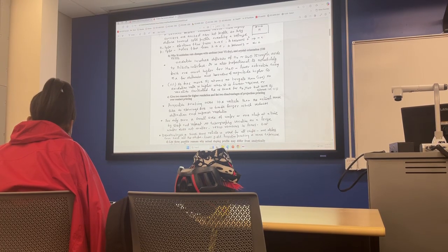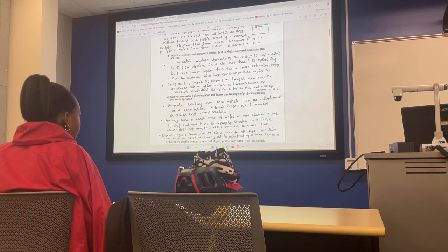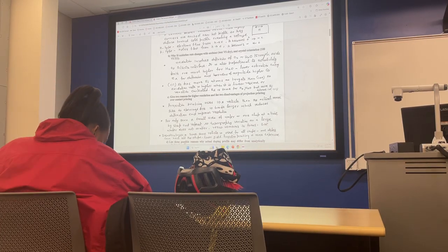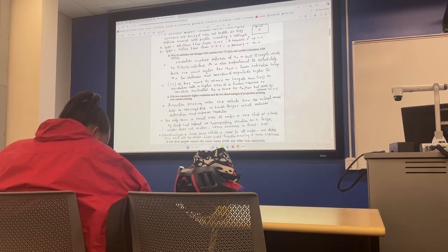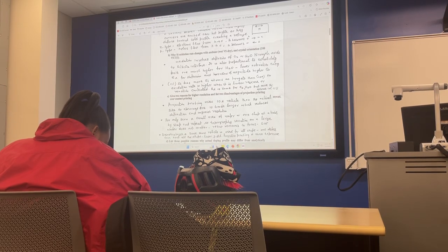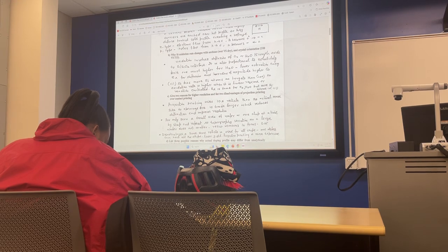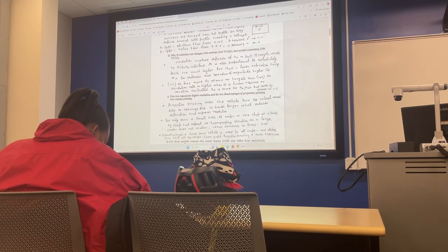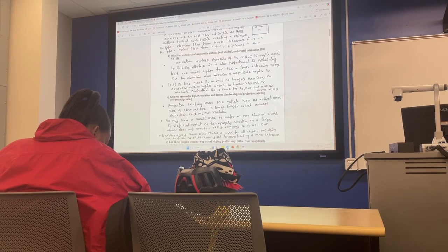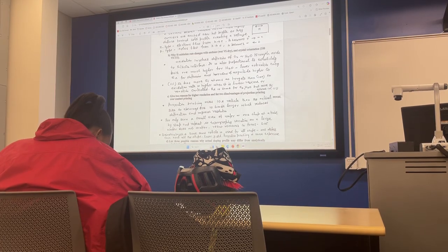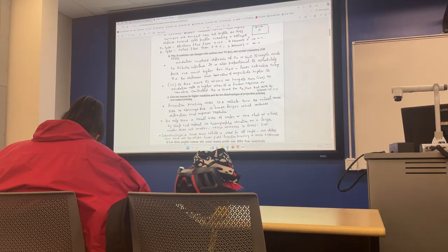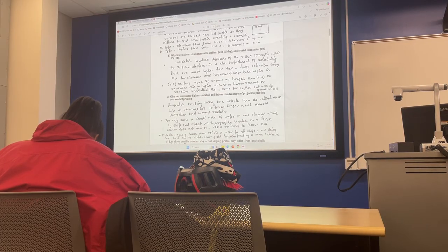But having a larger opening means you have less diffraction, right? Because the opening is much greater than the wavelength. Diffraction happens when opening and wavelength become comparable. But since I'm using a larger opening and then demagnifying it, there is less diffraction, and that was one reason for the resolution being better for projection.